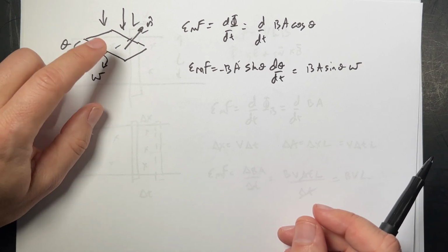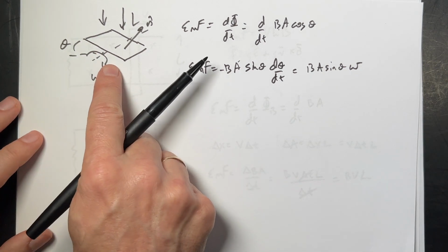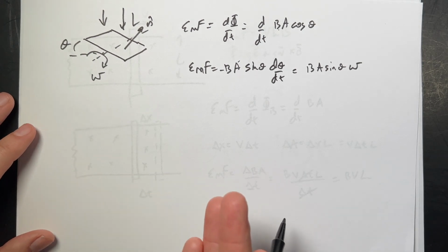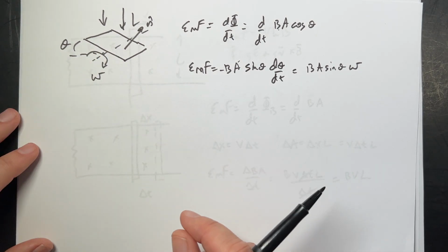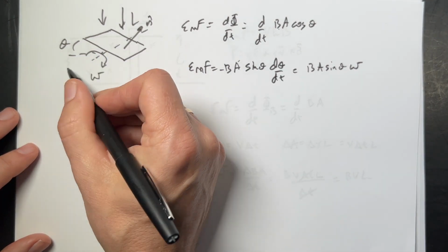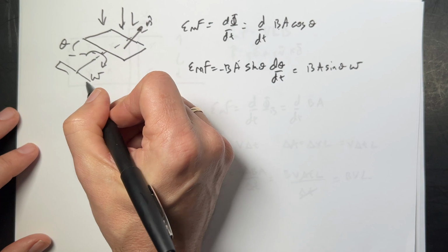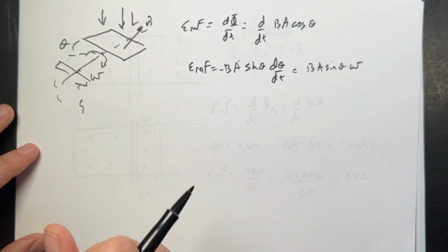And this is really important because most of our electric generators work this way. You can take a coil of wire, you apply it in a magnetic field, then you rotate it, and you get an electric current. And the question is, how do you make that rotate? A very common way is to have a turbine. So like here, we'll put some fans up here, like this, and then I'll have steam come up there and push it and turn it.